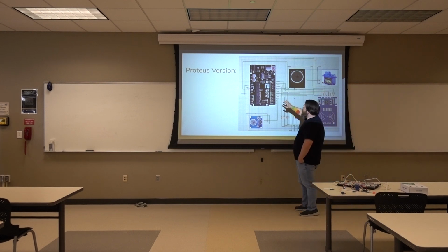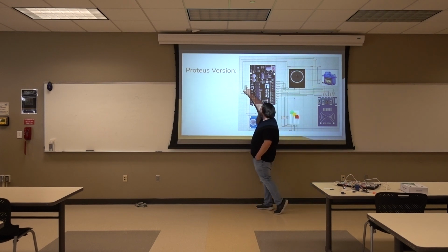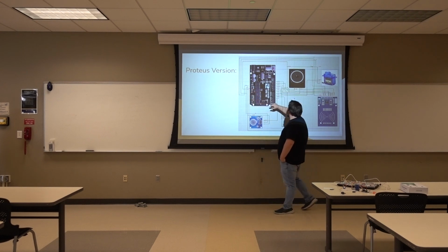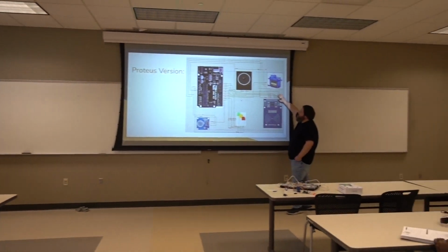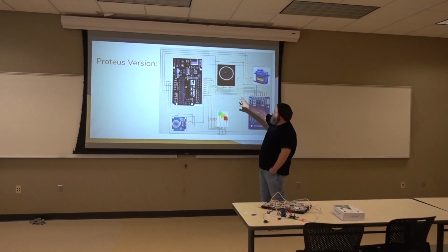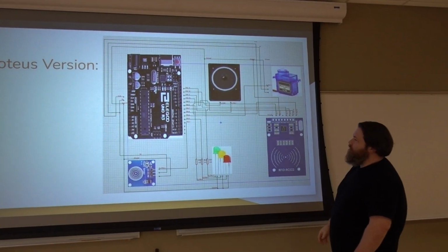I just want to point out that the RFID sensor takes a 3.3 volt power source located on the Arduino, so that we don't burn out our sensor. I added labels to the outputs for ease of use, to give you verification of where they go, because this can be a little confusing in this area.